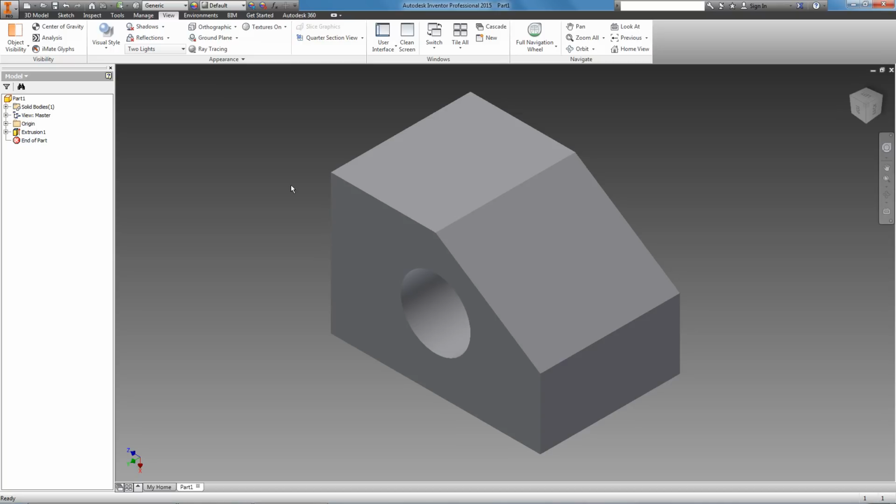So take your calipers, your micrometers, your depth mics, stuff like that, and go at it and make the object in CAD. Not only will that make that object easier to machine because you understand the object better, it'll also help you build your skills in the long run. Even if the object's simple, make it in CAD. It's also so you don't have to measure the object every single second when you're trying to recreate something. You're not like, oh, I forgot what this dimension is, I'm going to come over here and measure it 50 times.